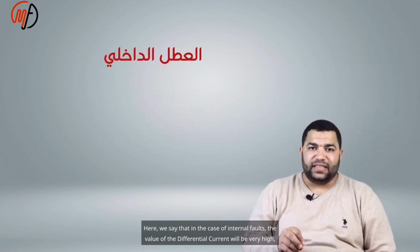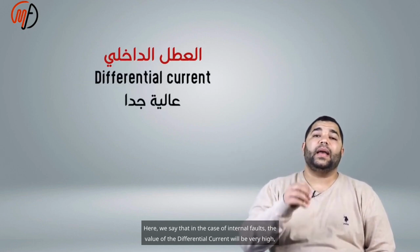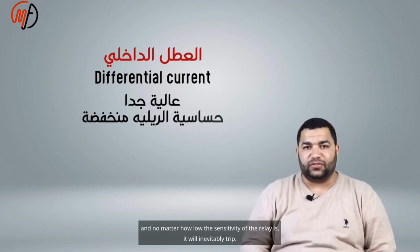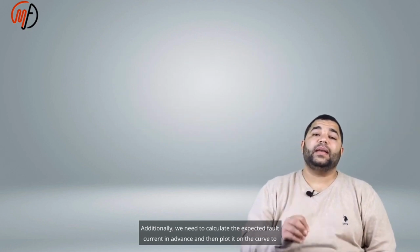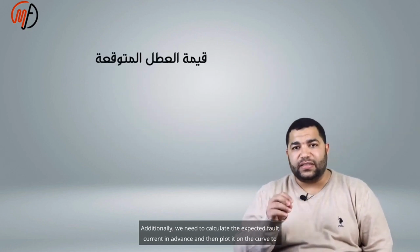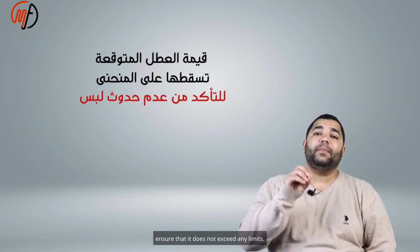Here, we say that in the case of internal faults, the value of the differential current will be very high, and no matter how low the sensitivity of the relay is, it will inevitably trip. Additionally, we need to calculate the expected fault current in advance and then plot it on the curve to ensure that it does not exceed any limits.